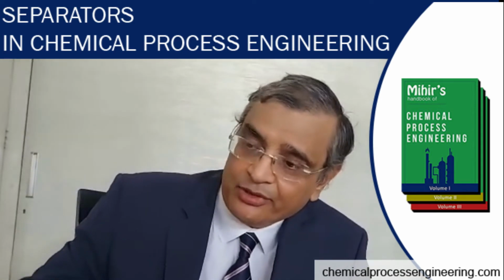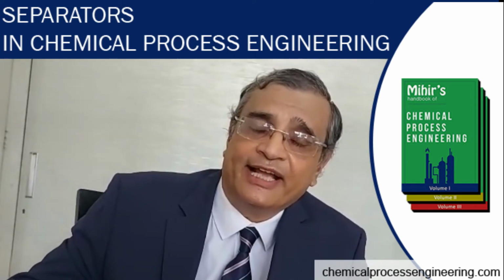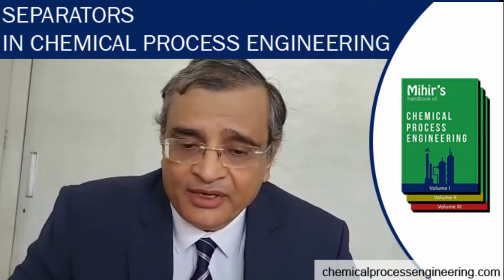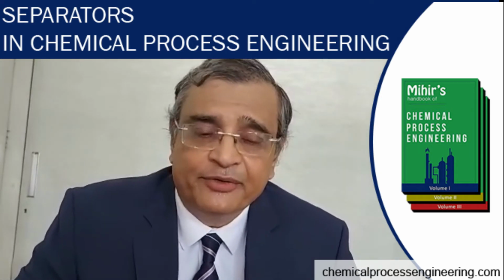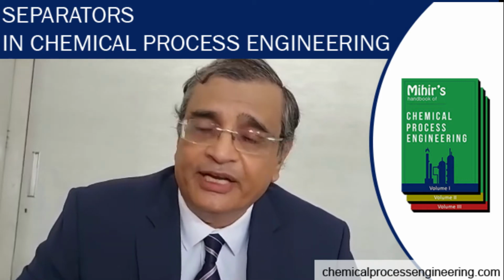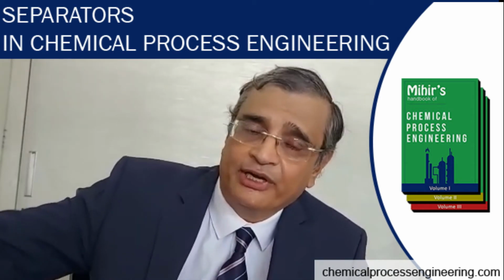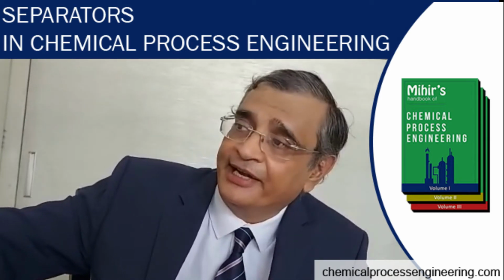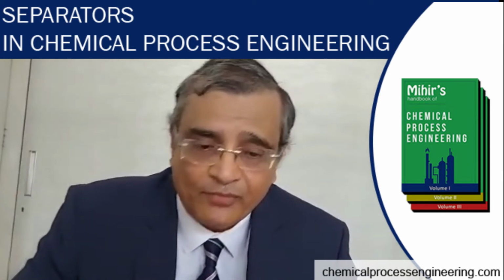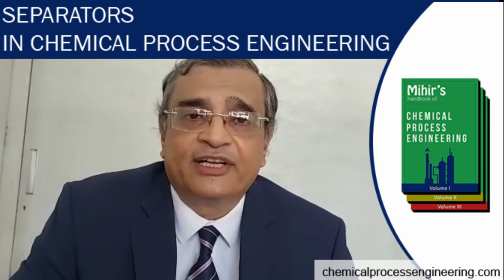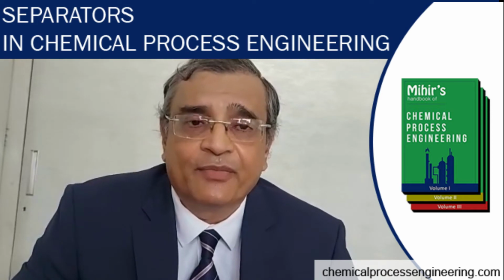Similar to that, in the outlet gas you can have mist eliminators, which is nothing but a mesh pad. You can have vane pack eliminators, or you can have cyclone eliminators also in the outlet for separation of the entrained liquid in the gas. Now this is as far as the two-phase and three-phase separators are concerned.